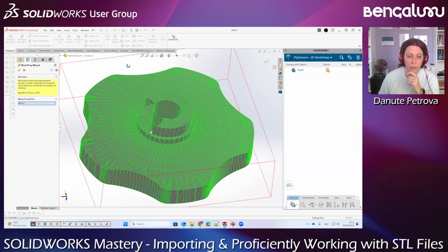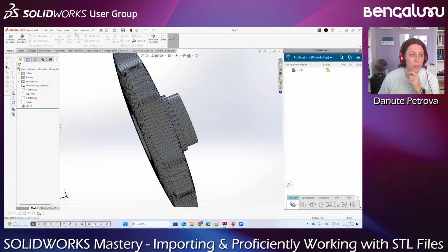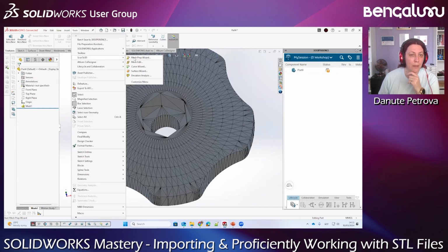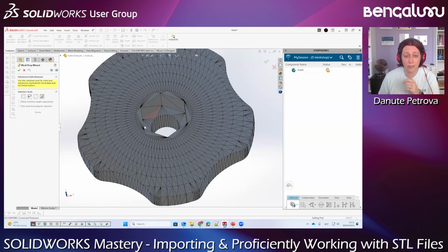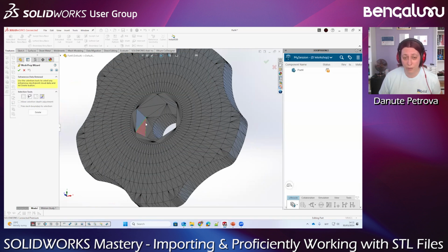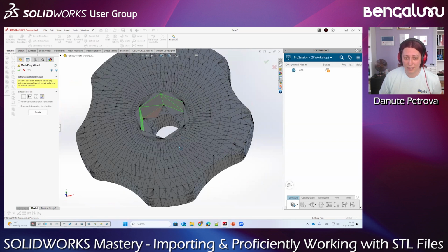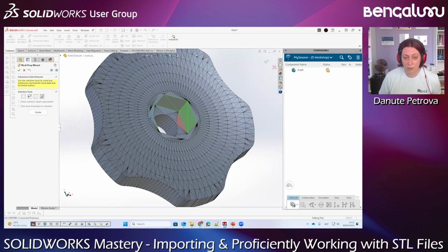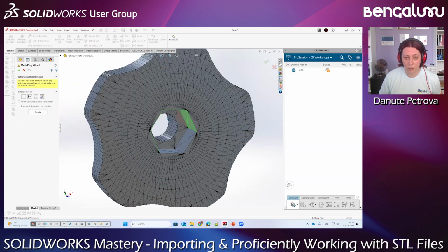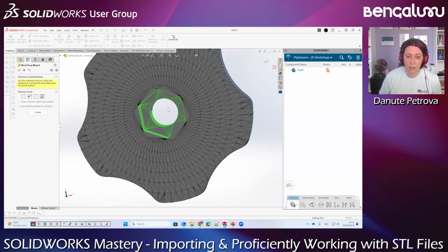So we are going back and going out actually of the mesh preparation wizard in this case. We'll start it again. That's why it's good before hitting delete to have a good look around if you haven't picked some of the faces. Sometimes for some faces or facets in this case, it's okay.